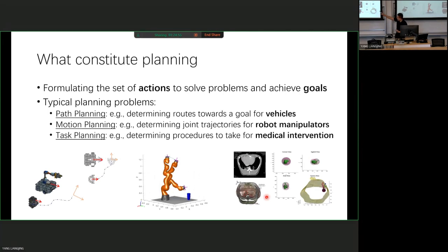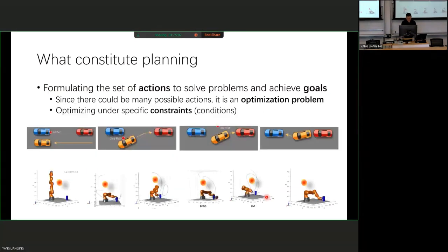Okay, so there are path planning and motion planning. Path planning means we don't care about the time you take. It's just the geometrical shape, the route that you should take. So in parallel parking, you can take 2 minutes, 2 hours, 2 days, it's fine if you are doing just path planning.